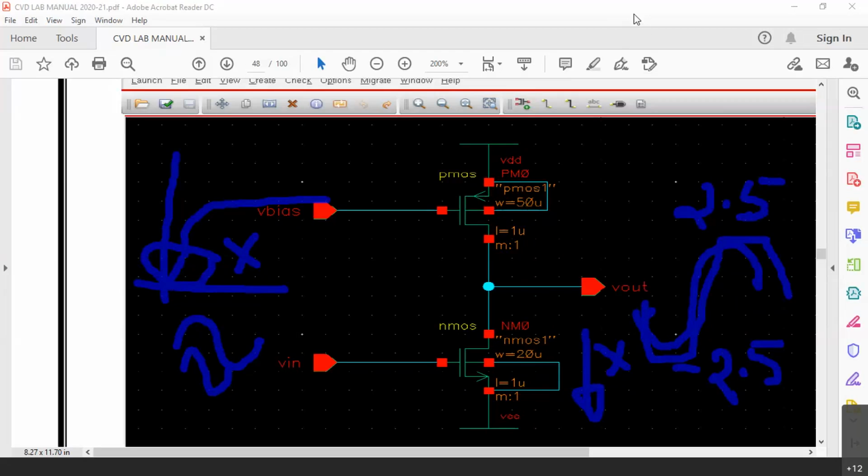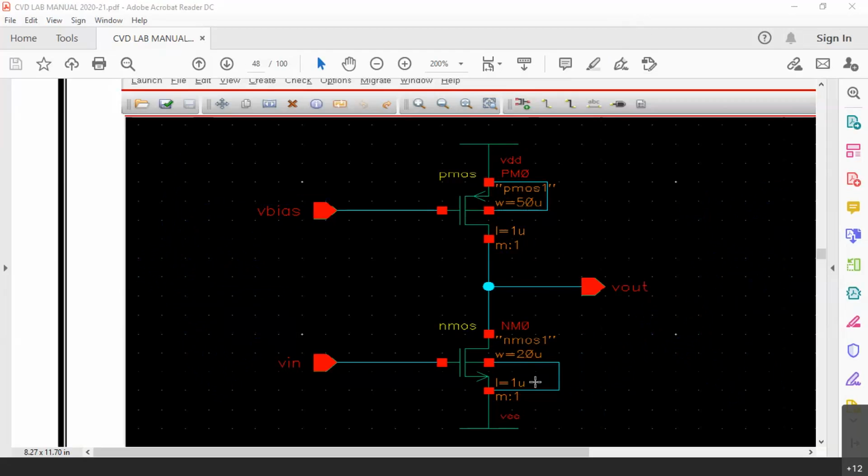Now, to prevent that, the NMOSFET should never go into deep triode region. So as this is going to work like a resistor, this also will come into a linear region and remain like a resistor. Now you will have a voltage divider network. Even when the input signal is rising fully, this NMOS will work like a resistor only. It will not absolutely close like a switch.